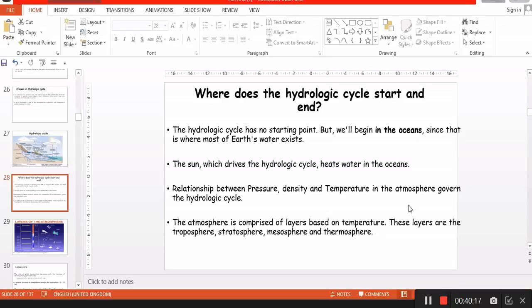That is very important. If you get groundwater, percolation is responsible for that. Sometimes we will talk about deep percolation. If you have groundwater, it is usually below the soil surface, so it is not possible for that water to evaporate back into the atmosphere. You understood or not? But if you have a certain amount of water moving into the oceans, then there is a possibility for evaporation. So we will see these things later, right? Okay, with that note, I am moving to this one.